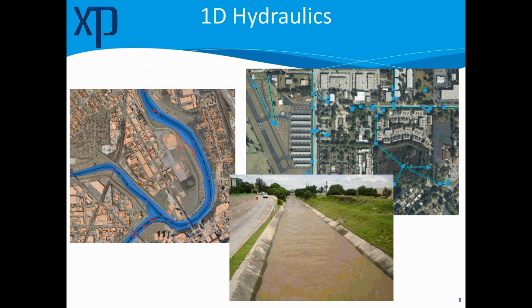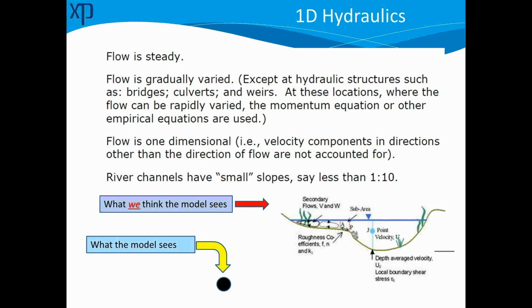So picking up that river model, that legacy model, it was one-dimensional hydraulics. We need to understand a little bit about one-dimensional hydraulics, and there are several assumptions that go into many of those models. I know there's a few communities out there that have unsteady models. There's a few communities that have full dynamic models, and we'll touch on that here, but just looking at the bulk, the preponderance of the legacy data that we have in the program, it's generally 1D hydraulic steady state, has to follow the assumptions that go along with 1D steady state flow.